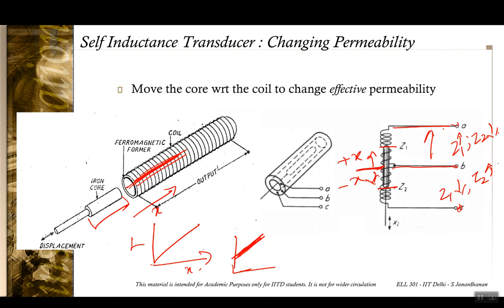And the reason for that is now quite obvious, because in either direction, for example, if you go in the Z1 direction, there is more part of this magnetic former that is linked into Z1, and consequently there is less linkage in the Z2 part.